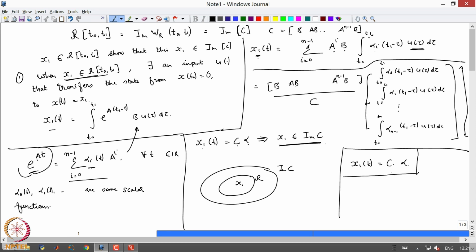So, when is this equation solvable? Well, this alpha is C inverse of x1, and this alpha has the information of my unknowns, which is my input. So, this C, which is the controllability matrix, for a solution to hold here, the C matrix should be invertible, right. This is a little interpretation when k equals 1. For higher cases it may have a different interpretation, but all the undergrad texts on control will start with deriving the Kalman rank condition of this form. When the inputs are just scalars, just u is in R, then I can interpret this as just a solution to a linear equation, which is possible if and only if C is invertible.